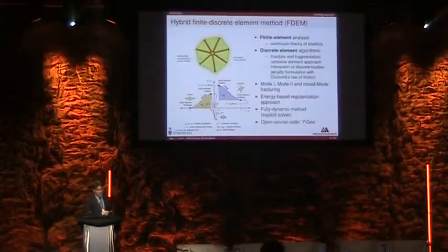The characteristic here of the method is the constitutive model that is implemented at the crack element level. Those crack elements can fail in tension or in shear, and there is a post-peak displacement softening behavior which is governed by the Mode I and Mode II fracture energy in tension and shear respectively. The code that we used was an open source code, because in that way we have the flexibility required to add features to the method.